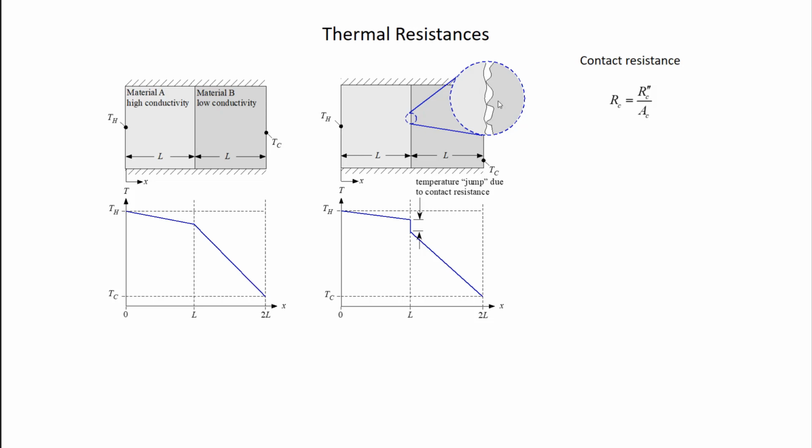And that comes with a penalty, right? That constriction causes a thermal resistance. And so at the macroscopic level, if you zoom out, what it looks like to us is that you have a temperature jump at that contact, right? So there's a temperature difference that's required right across this contact to drive the heat through these little touches where the asperities touch one another.